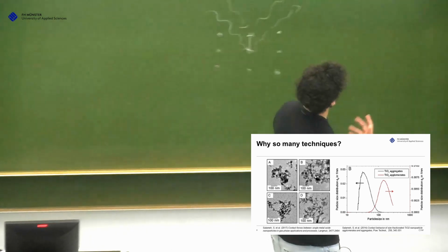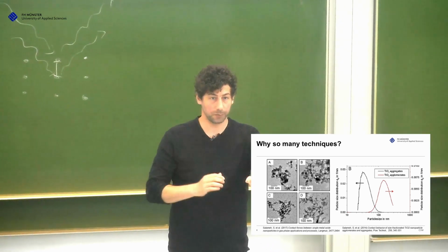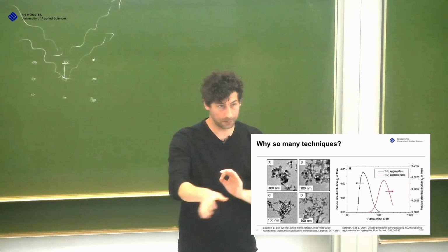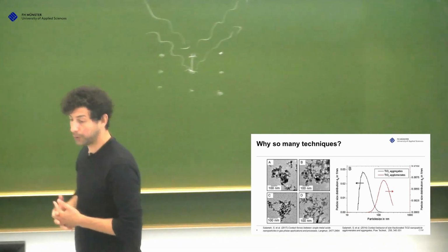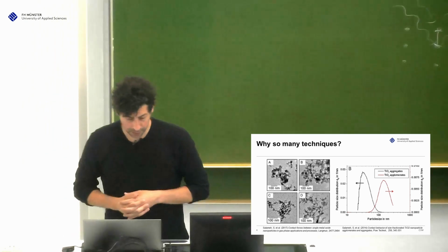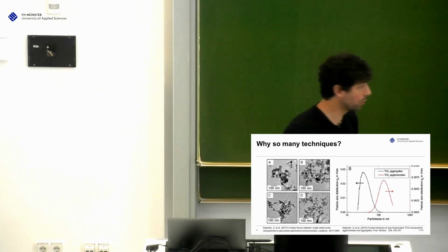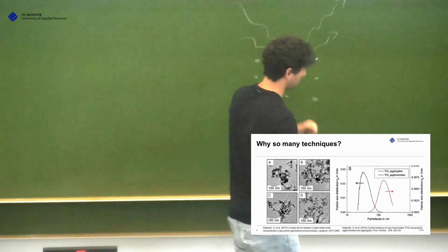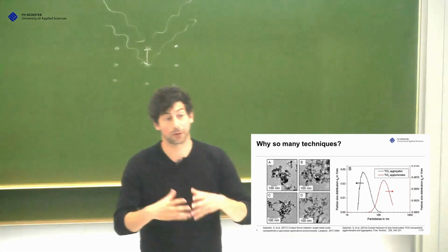What you do is you assume spherical size, and then you put spheres with a software where you're sure this is a primary. Not all of them, you look at multiple pictures, and in this way, you can get primary particle size. And then you get a size distribution, and if you want to be sure, you make an XRD, because XRD gives you also sizes. From the peaks, you can calculate the size of the crystal.